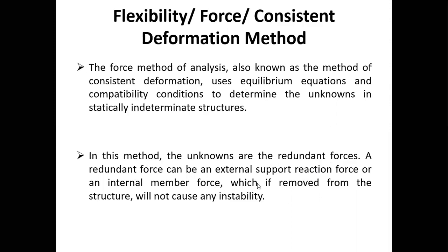A redundant force can be an external support reaction or an internal member force, which if we remove, will not cause any instability in the structure. So this is basically the approach of analyzing a structure using the flexibility matrix method, or the consistent deformation method. We simply remove any of the support conditions or modify it in order to convert it into a determinate structure. Then we'll simply analyze the structure using the conditions available.